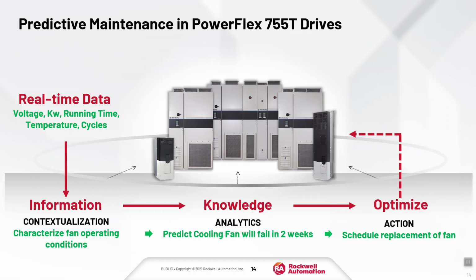Since we know the stress limit of our cooling fan, and we've done thorough testing on each one of these different criteria, we can predict when the cooling fan will fail, generate that insight for a maintenance person, and then schedule downtime instead of leading to an unplanned downtime due to a fan failure. In addition, in this PowerFlex family of drives, we've made fan failure extremely simple. So this is all about reducing unplanned downtime.